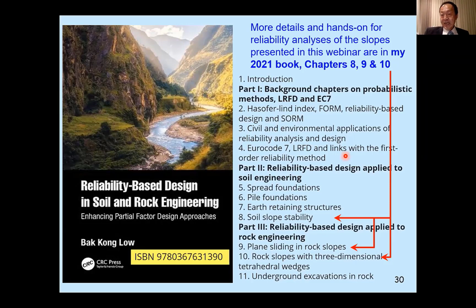Parameter A may be more sensitive in this case than B, but in another case it is B more than A. Monte Carlo simulation, the one that I'm familiar with, can give you the probability of failure. But I think as engineers, we also like to know something about the sensitivity of the parameters, as revealed by the design point.